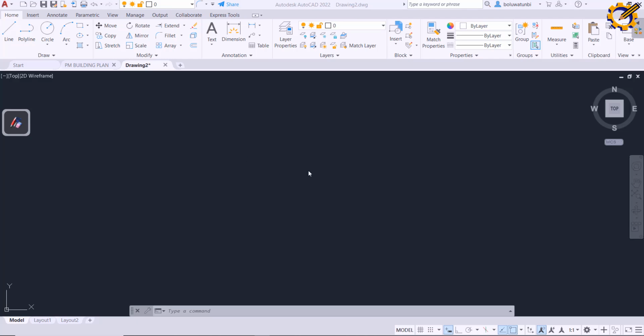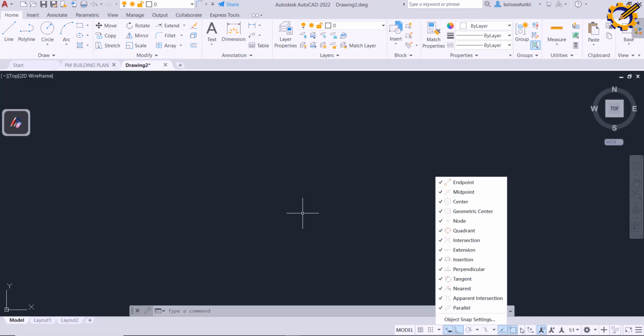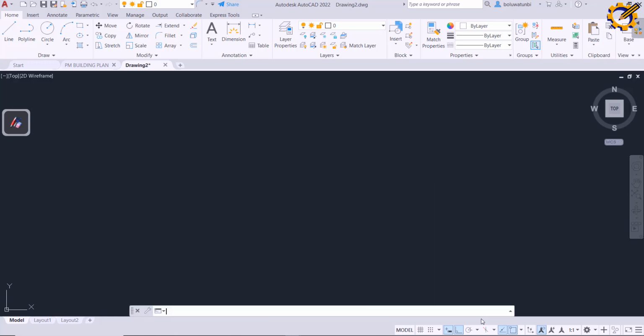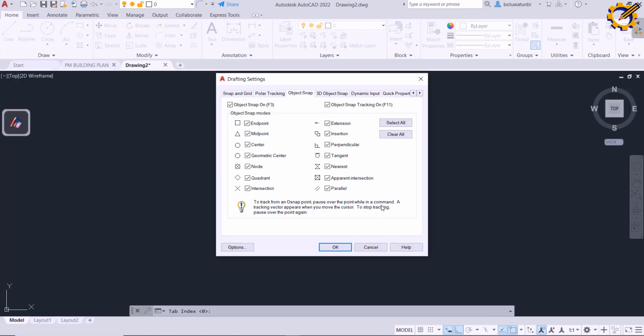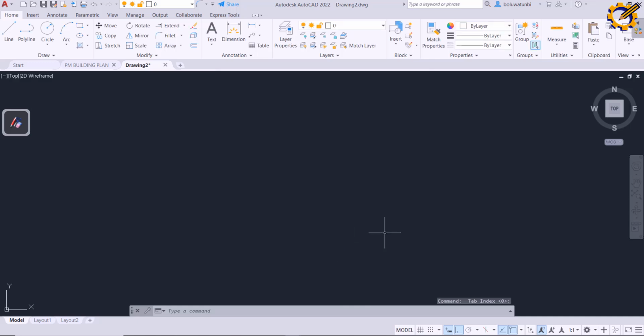As we have constraints in there, we also have constraints in AutoCAD. So I'm going to come to this one, that's auto mode F8. I'm going to switch my F8 on. Now to my object snap, I'm going to press the arrow beside it. I think I've switched on everything there, so I click select all, and I switch everything on. So that is that about that.